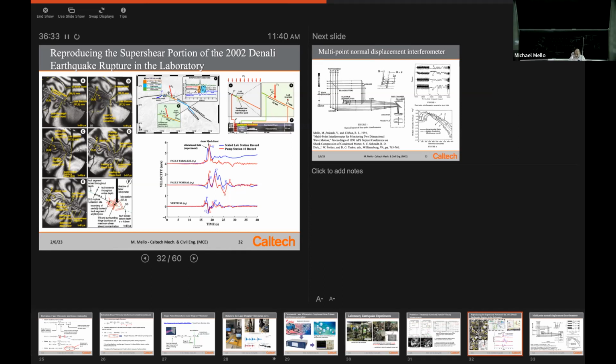But there were some stations there, fortunately, that also recorded the ground motion as the rupture swept. And this is how seismologists knew, forgetting the blue curves momentarily, the red curves see a fault parallel component dominant over the fault normal by a certain percentage, which is unusual. You never see that. And so then people did analysis and said that must have been super shear.